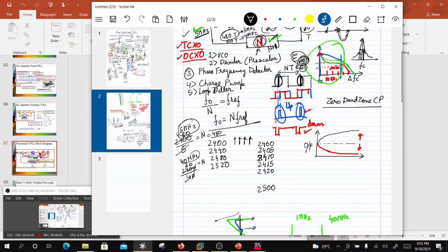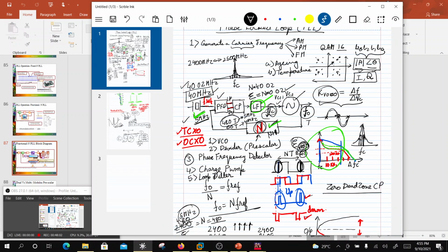Now these loop filters, something you have to see is that first order, second order, and third order loop filters, and we will prove it, are basically stable. And beyond third order you are going to see complex poles, and complex poles mean ringing, or spurs.